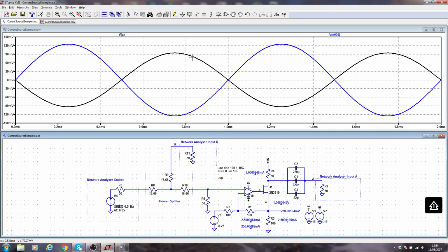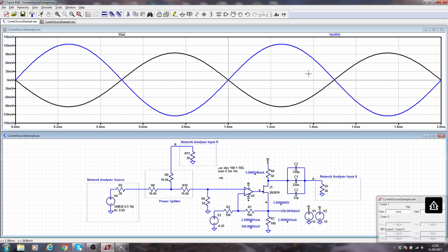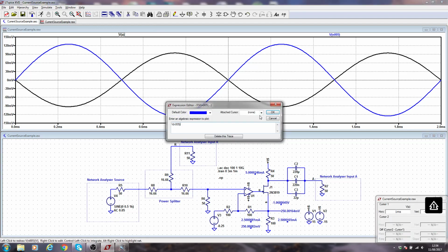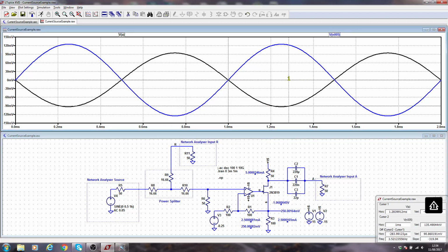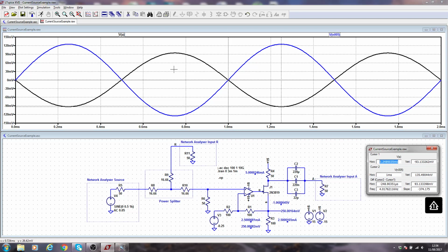We can get the gain by another method if you like later, but if you want to do it on here, the way you would do it is right click, add a graph, add a cursor, right click, add the other cursor, then you take them, I don't know, probably to the peak I should think. We'll try and find the top, it's probably there. If I look at the graph, it will tell me. Where's number 1?